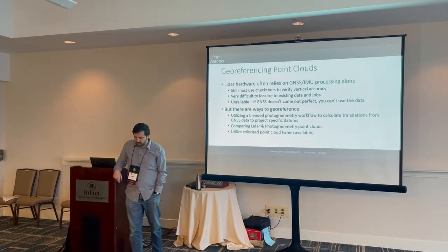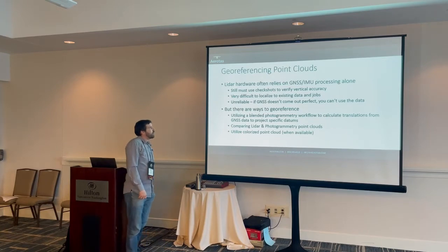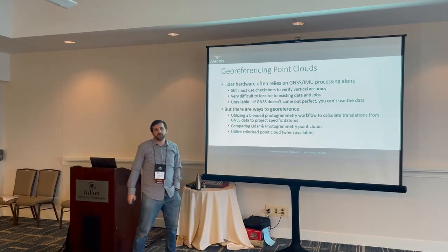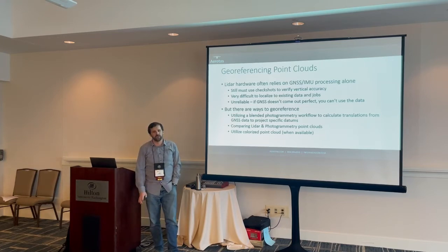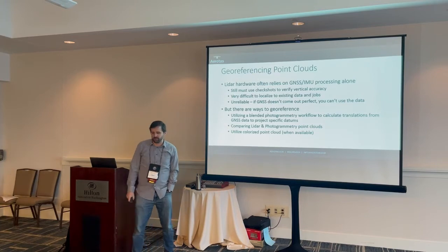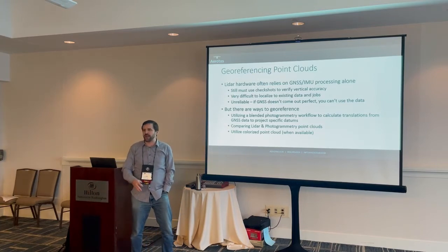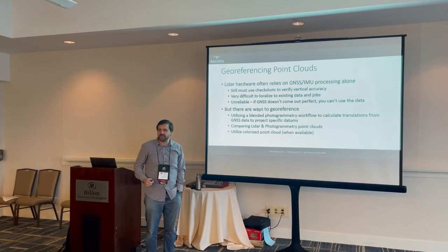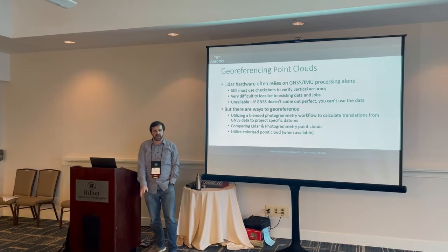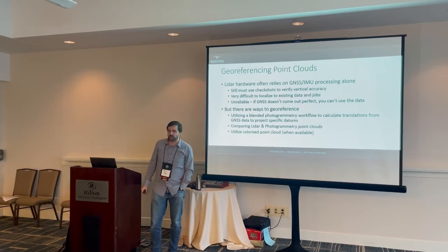Likewise, part of the reason we talk about that, a lot of LiDAR hardware relies on GNSS and IMU processing alone. We have talked a lot about it, and GPS is very, very good, but it is not perfect, and it's not good at checking itself. Especially because the drone is flying, you can't reoccupy a point. You can't measure a point once at the beginning of the day, and then again at the end of the day, just to verify that your systems are all still working and that you don't have systematic drift over the course of the day.